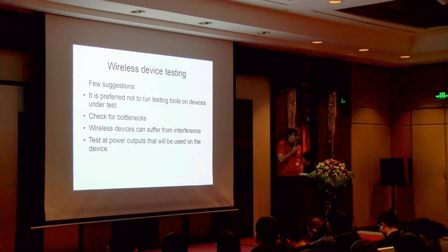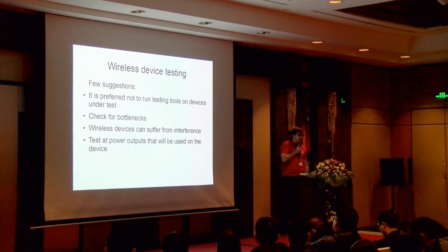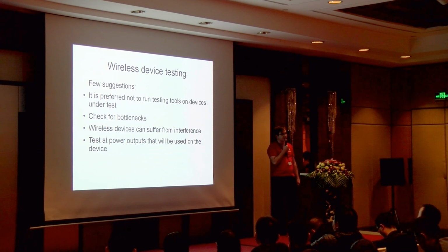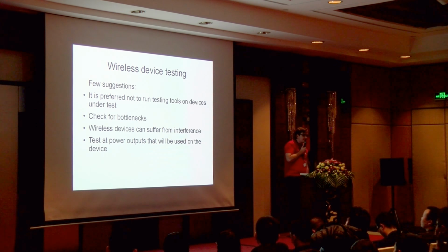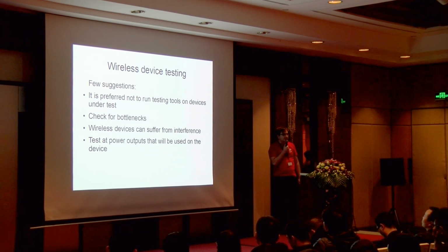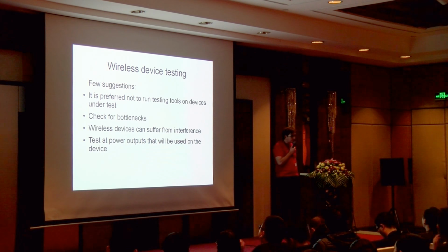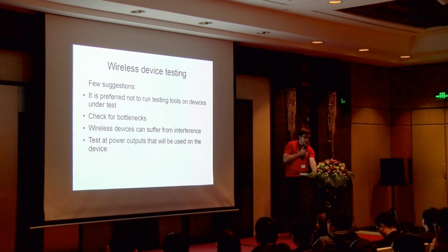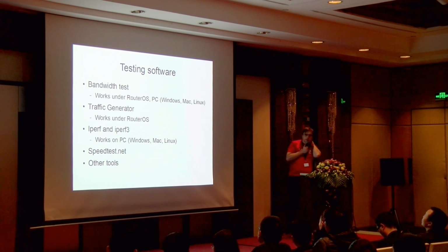Wireless devices suffer from interference very much. Don't test 20 devices on the same frequency in the same room. Tested power outputs used at the device and distances should be the same as you plan to implement your link.